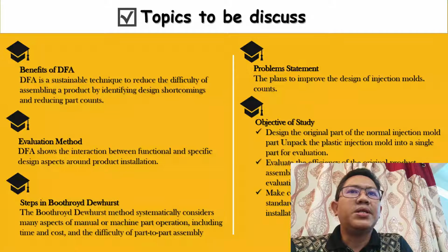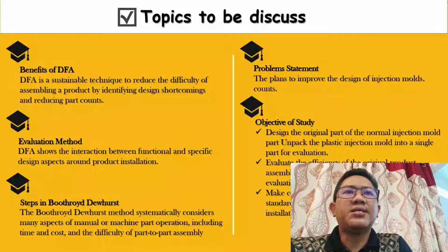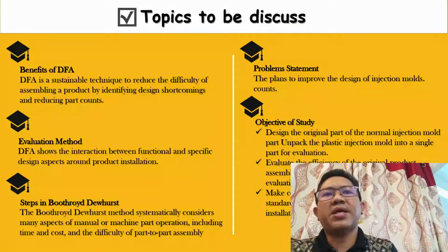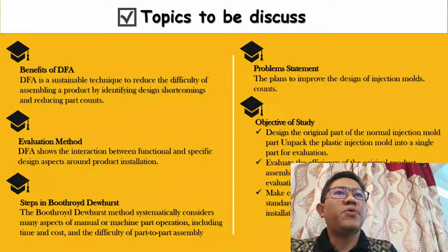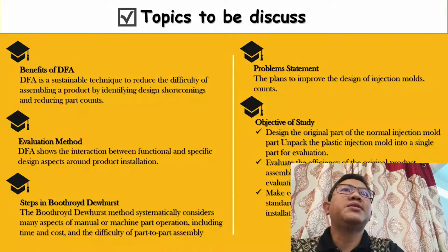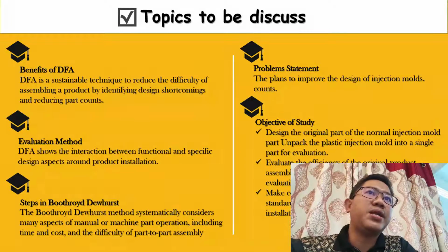The Boothroyd-Dewhurst method focuses on designing individual parts and matching of component parts, regardless of the combined factors of assembly: selecting the installation method for each section, and each section analyzed for the given installation method. And from here, next we improve the design in response to the shortcomings identified by the analysis and circle back to step 2 until the analysis produces an adequate design.